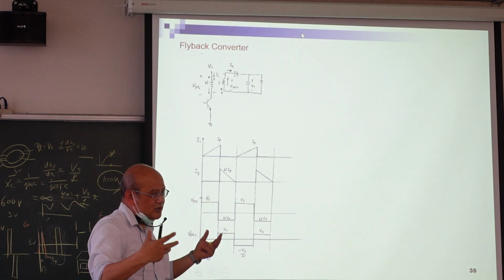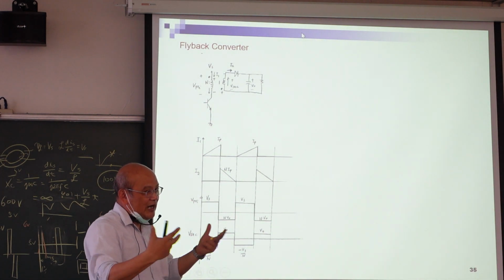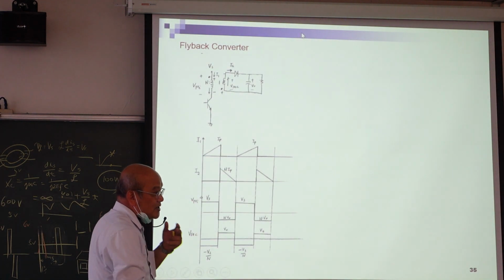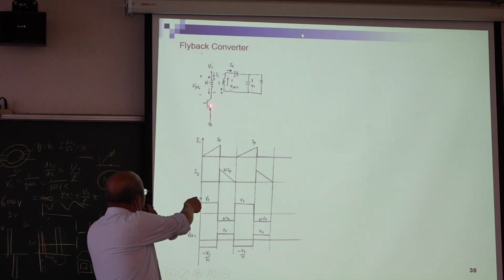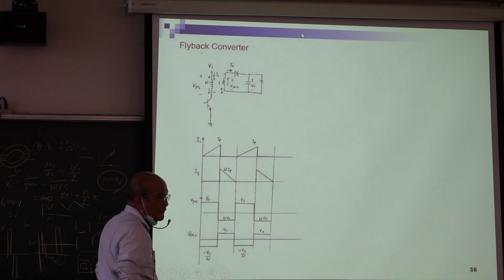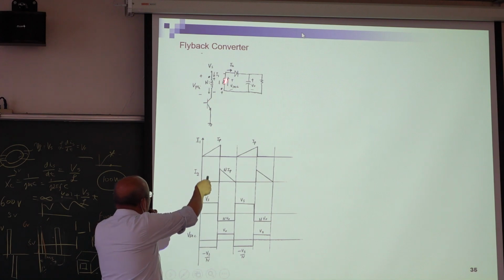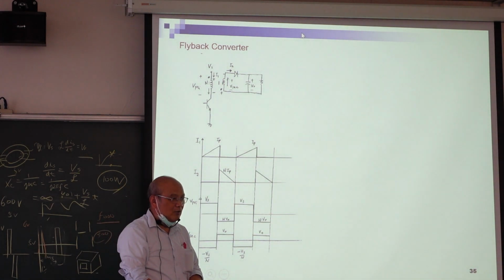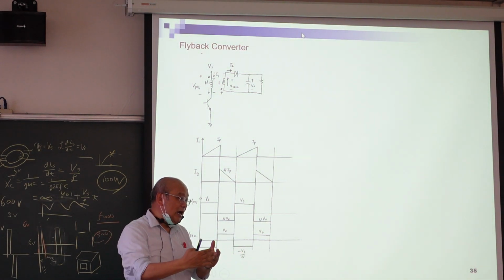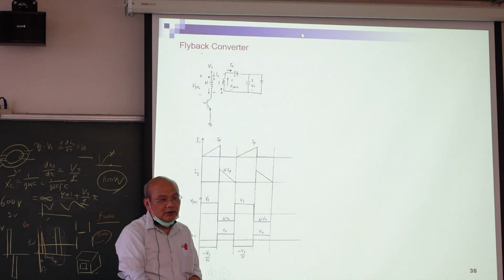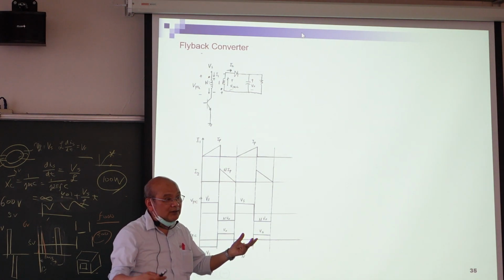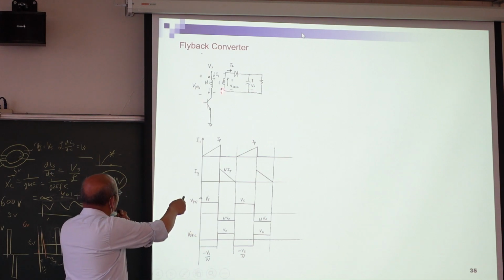If your circuit has no switch, can you design a converter? Impossible, right? So can I remove this switch? No. Can I remove this transformer? Without a transformer, can we isolate input and output? No, right? So the transformer is required.